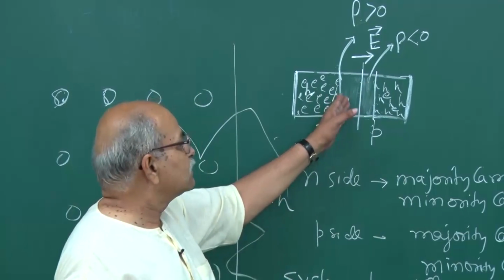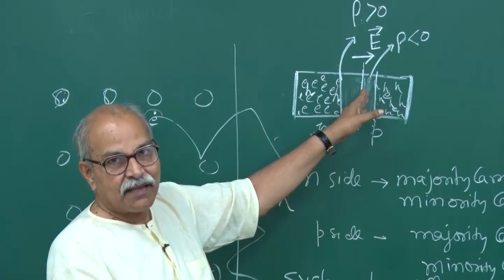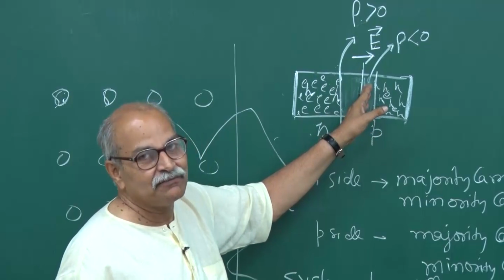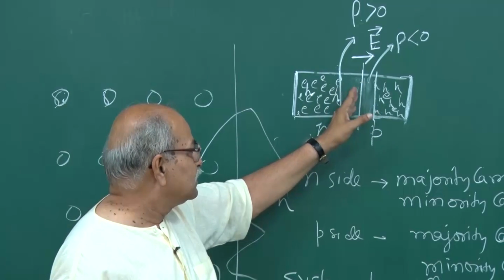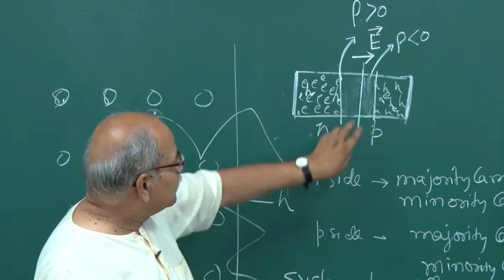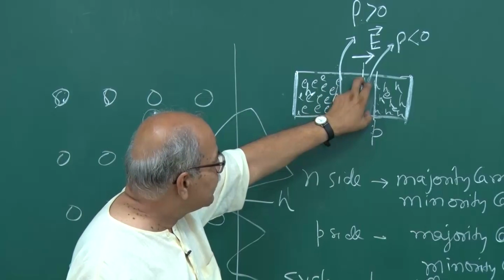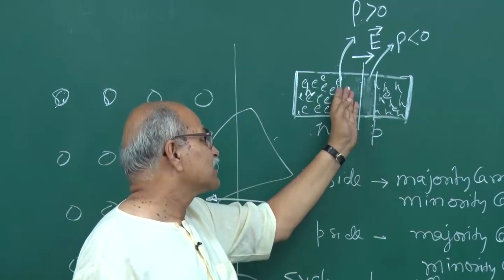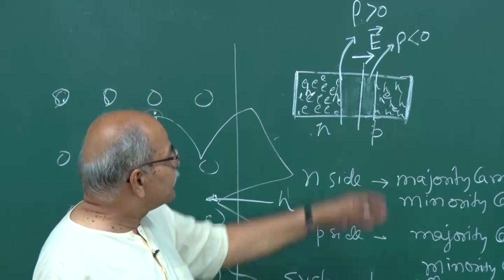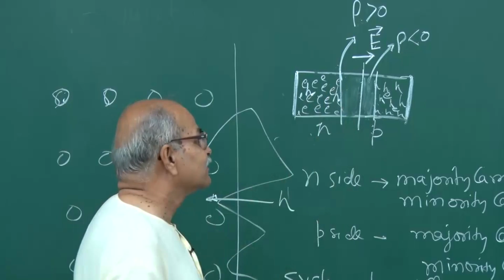The electrons which are diffusing to the right, because of the large hole density there, are trapped, and if there are holes left, more electrons will come, so this width will adjust itself. As many holes as are here, that many electrons will go from this side and fill them, and the same both ways. So, what you find is, yes, there are charge densities, but you do not have charge carrier density.